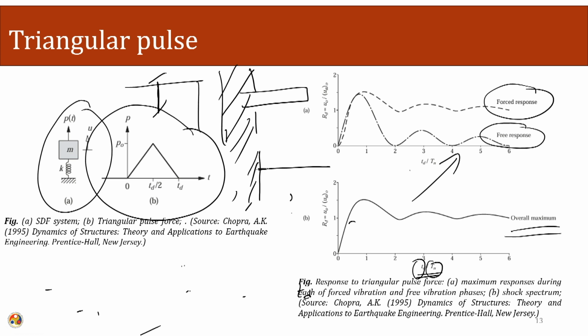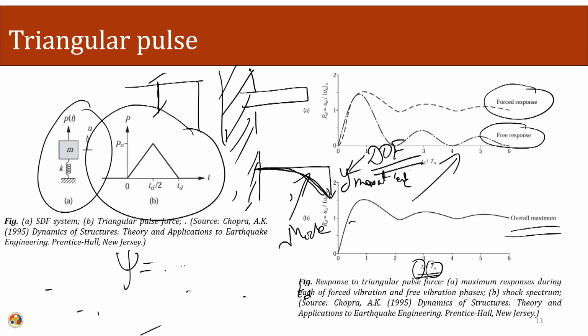When we are dealing with the cantilever, we can choose the degree of freedom as y max at the end. So, the degree of freedom becomes the maximum deflection at the end, and this becomes my mode shape. From there, again, the shape function will change.